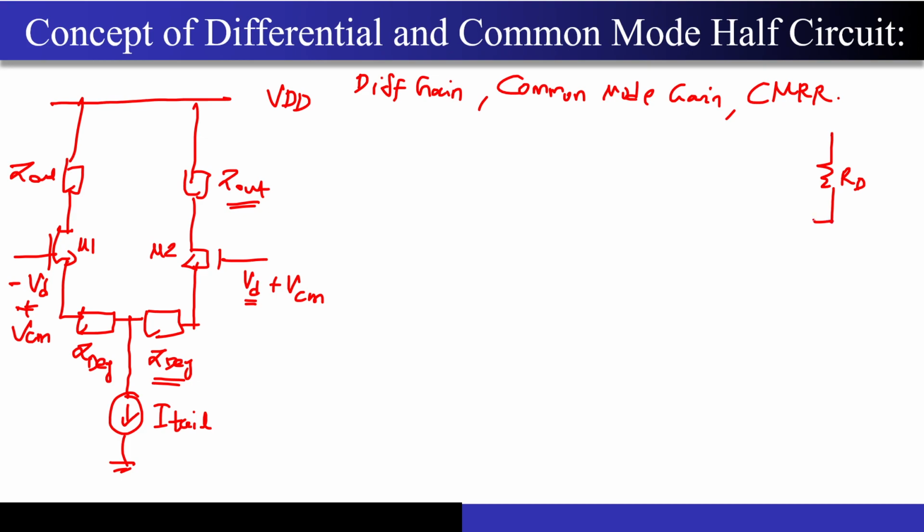Remember, you have a huge chip area. Correct? You may be designing the entire radar transceiver or communication transceiver, which may be very, very complex. This is just one of the circuits present at the baseband part of the transceiver. Now the problem is this particular thing that you are seeing over here. Any noise can get coupled at this particular net, and from where the noise can get coupled? Remember, you have RF transceivers, right? RF transceivers will usually have the inductors. Correct? Now just tell me what will happen if I pass a current through this inductor. What is going to happen? AC current, I am talking about AC current. What is going to happen?